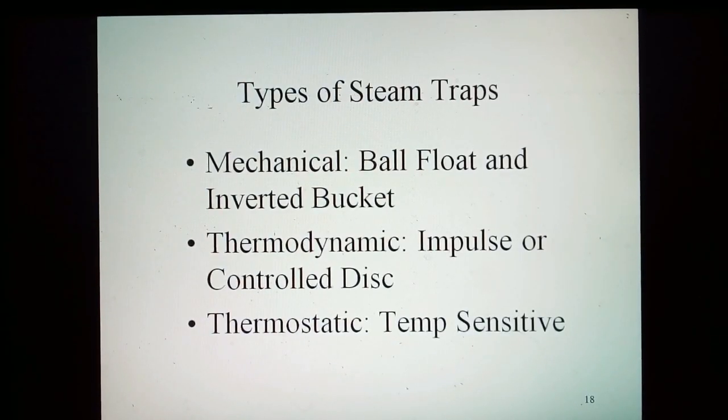Steam traps fall into three categories. Mechanical steam traps are of two types, which are ball float and inverted bucket. Thermodynamic steam traps, which are also called impulse or control disc. Thermostatic steam traps, which are temperature sensitive.